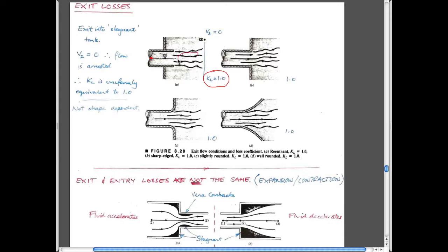This is the submarine that's sitting in the tank, as we dealt with. And this is the stagnation point on the tip of the submarine, because the water coming in here into this big tank has to decelerate to zero velocity. And so different from the geometries with the tank that we looked at, where this geometry was worse than this geometry, which was worse than this geometry, and is worse than this geometry in terms of the losses as you go across it, they're all roughly equal to 1, which basically means that you're going from some velocity you have in the pipe to zero velocity.